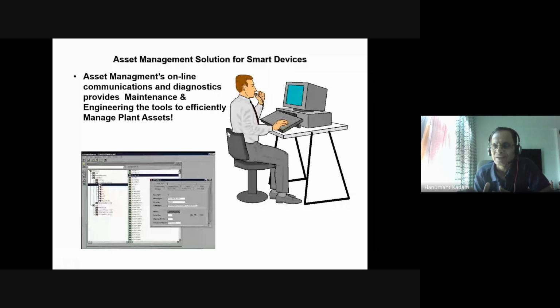Your HART signal, the analog part, DCS cards are taking, but the digital part, which you communicate with the transmitter, that feature in the DCS cards is not incorporated by any of the manufacturers. So everybody suggests a separate workstation with a HART modem, HART software, connected to your critical transmitter device, and you'll get such type of screens as that one.